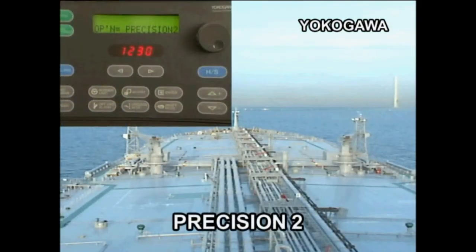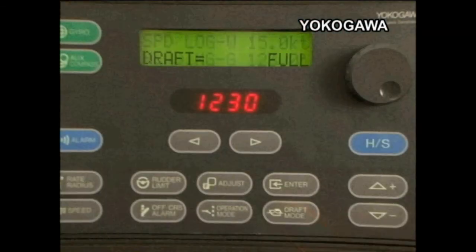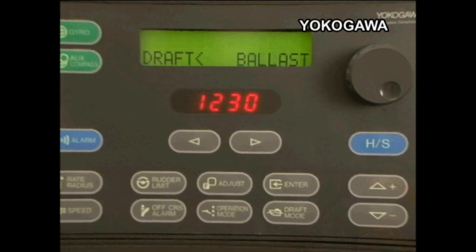Precision 2 is suitable for automatic steering when giving priority to course keeping in congested waters. Yokogawa's system offers a mode for draft data input. Draft mode has three settings: full, middle, and ballast. Should the gyro compass break down, the signal from the magnetic compass can be used in place of the gyro compass azimuth signal.